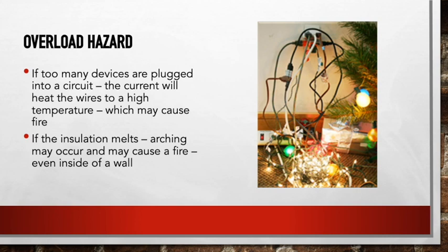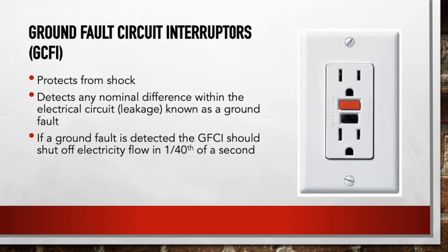So overload hazards. This is something our parents told us about when we were a kid. You don't want 50 things plugged into one outlet. What can happen is, if the circuit doesn't trip, things heat up too much, whether it's the plugs or the receptacle, and that heat can burn through the insulation and then cause an arc, as well as a fire. And we've all smelled heated electrical insulators before.